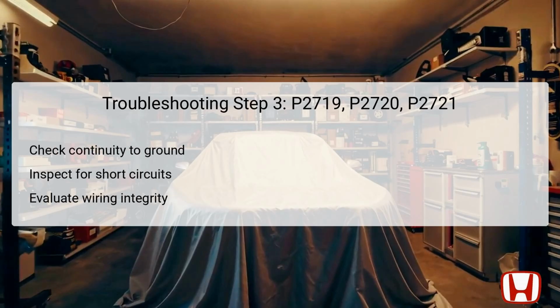The third troubleshooting step is crucial in isolating further electrical issues by conducting a shorted wire check. In this test, you will again start with the vehicle in the off or lock mode, ensuring all systems are inactive and safe for inspection. With the TCM subharness 26P connector and TCM 58P connector still disconnected, you will check continuity between specific test points and the vehicle's body ground. The test points to focus on are TCM 58P connector terminals number 6 and number 53.